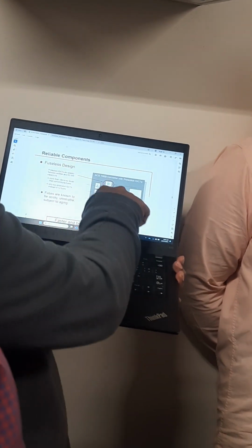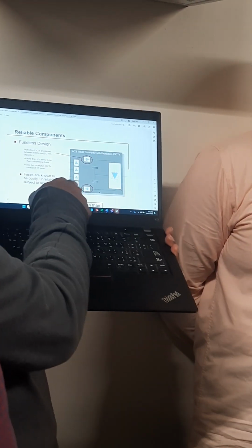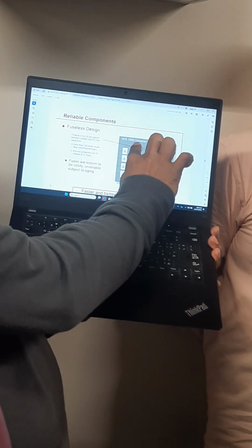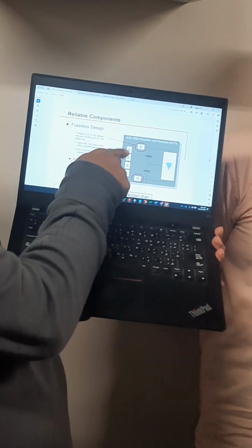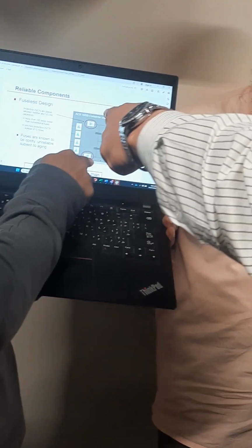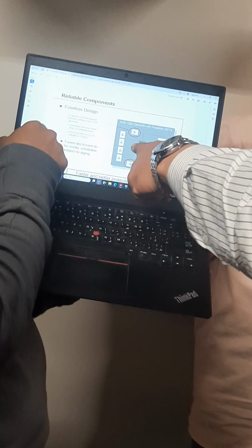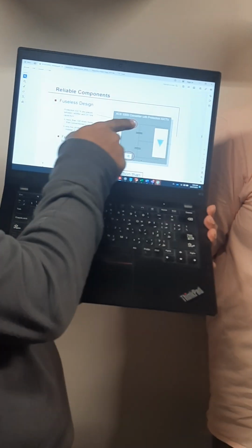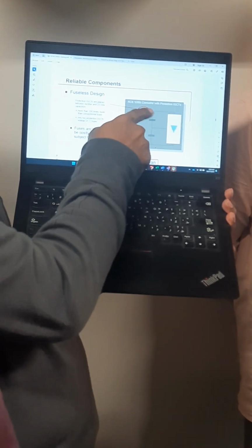You can see from this one, this is the thyristor diode part, and this is the DC protection IGCTs. This one is for the thyristor, where we convert to DC. In the DC lane, we have protection IGCTs, so any short circuit here, this will open.